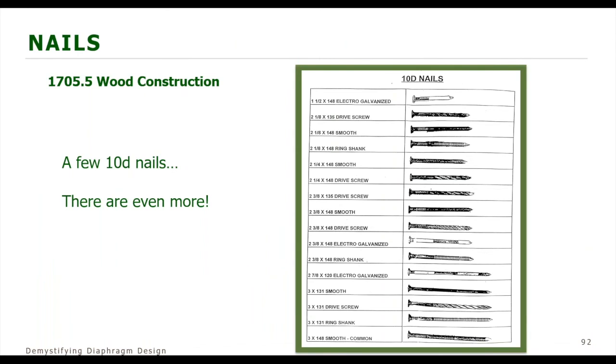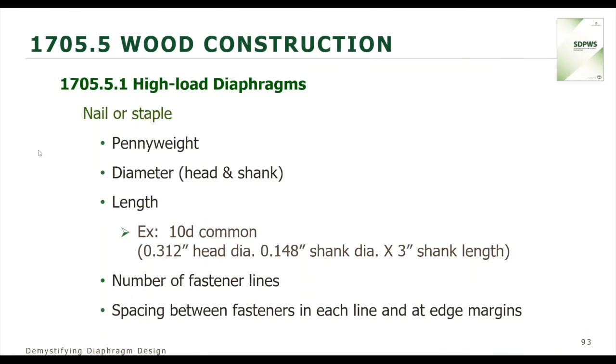And then the last thing to check of the special inspection checks is the nails that are specified. Now, I know in the olden days, older engineers used to say 8 penny nails or 10 penny nails, but that really doesn't cut it, because in this example for this slide, 10 penny nails could be any of these nails that you see here. So there could be multiple types of nails out there by just specifying 10 penny nails.